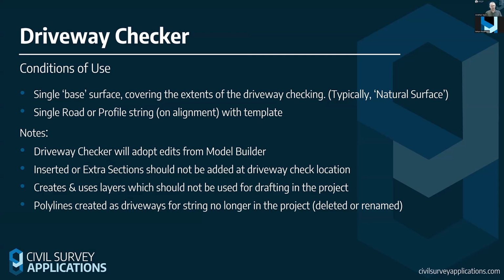And also the polylines that we're going to be creating in literally about a minute are linked to a string name. So if you go and rename that string or delete that string, essentially those polylines don't get renamed. The layer that is used to create them is no longer functional and you have to go ahead and recreate them. So just be aware of that up front before you start to use it.